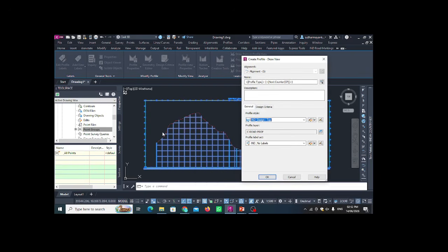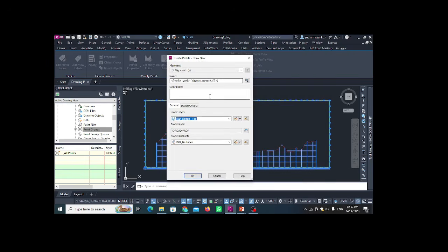See, this alignment we create is to check the ground level at the whatever the best location we set into the surface. Now we set the design profile. So now if we want to manage the cutting and filling part, so this is the design profile. This is the profile based on our original road is going to be created.